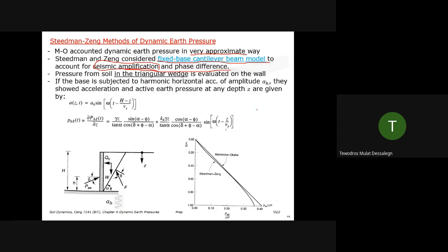Now, what did I say before? If you have a building with, let's say, 10 stories or 5 stories, I said, if you have a seismic input here, is it applicable at the roof level for design? No, right? The building amplifies. So the acceleration you have here is maybe 1G, but by the time it reaches here, the building amplifies it, depending on the flexibility and the period. And even resonance may occur. If this building resonates with the input motion, it amplifies a lot, right? 1G may end up being 5G or 10G.